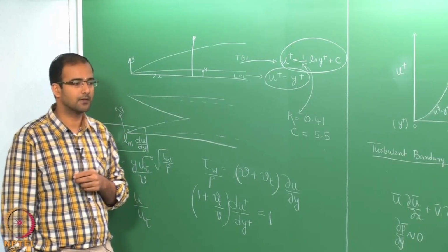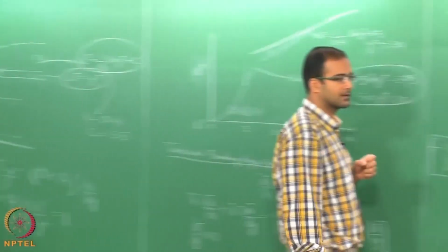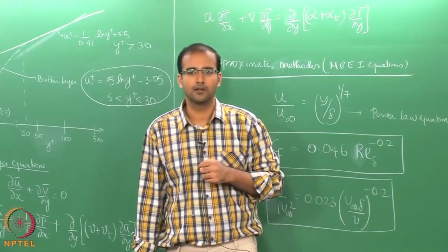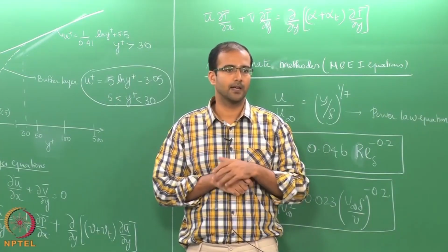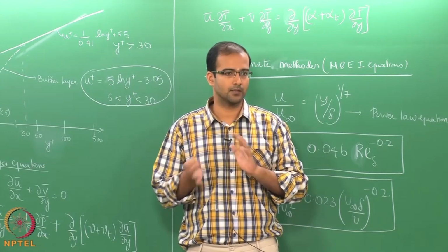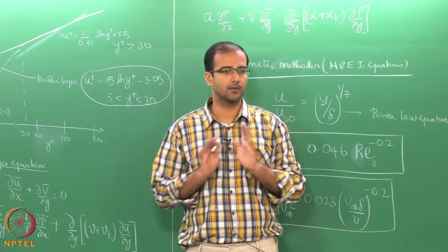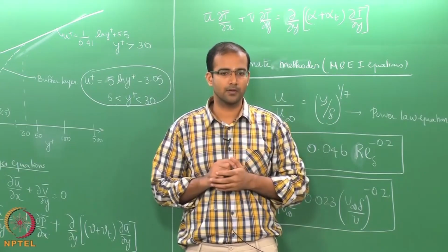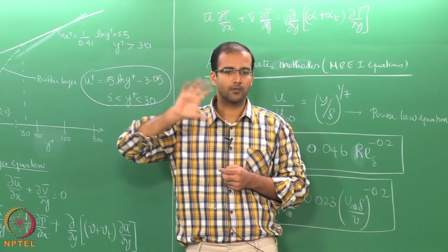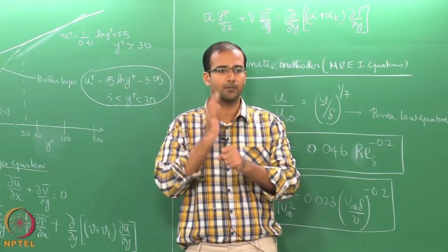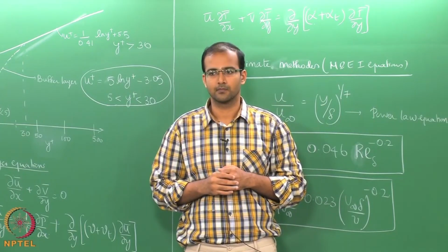So, what we will do is we do not actually solve the energy integral in this case, but we will try to find an analogy between the momentum and the energy transfer. We already saw in the laminar boundary layer there is a clear analogy between the two. If you replace u by u infinity with theta, the structure of the profiles as well as the equations become identical, and especially if your Prandtl number is equal to 1, they are exactly the same, right.